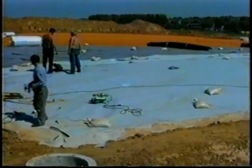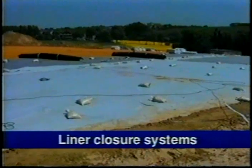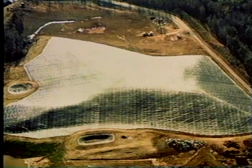Once a landfill is filled with waste, a capping system, multi-layered like the liner system, must be constructed over the top. The geomembrane in the cap is not in contact with the leachate, but it must prevent rain and snow melt from migrating into the landfill.